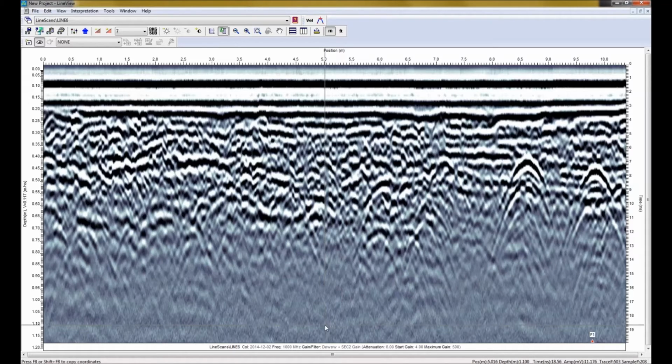And it is radio signals from other radio sources like radio stations and cell phones, TV stations, walkie-talkies, all sorts of other radio sources. Because remember that a GPR receiver does not just receive GPR signals. It receives all radio signals in its bandwidth. So signals from other radio sources are collected and will be displayed in your data. It's very important to remember that they are not GPR signals and should not be interpreted as signal in the ground.